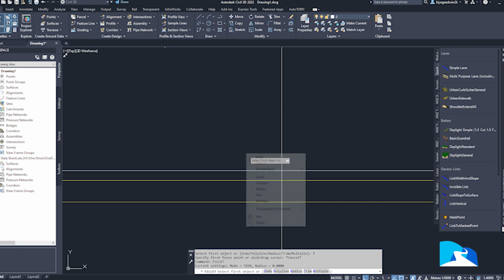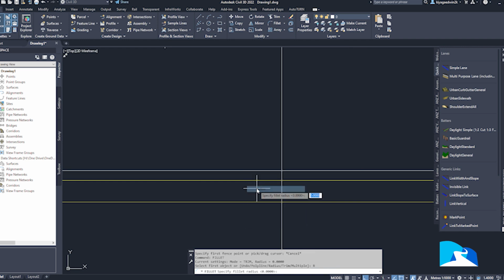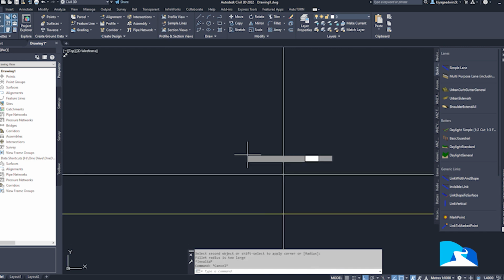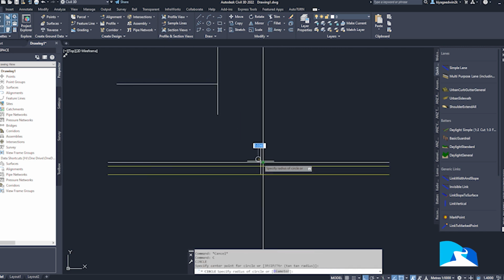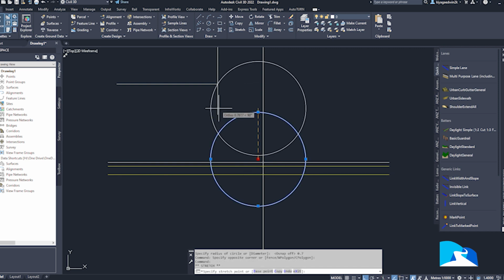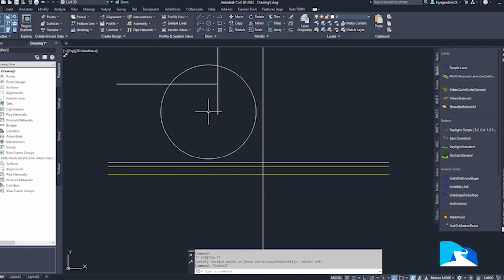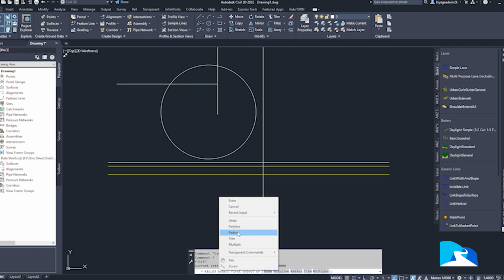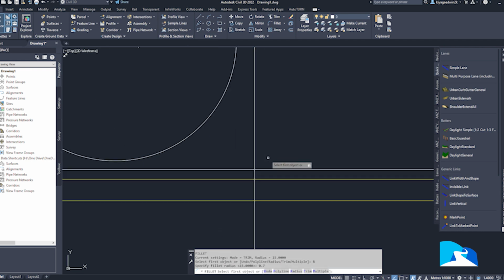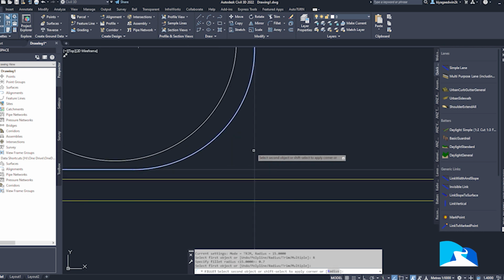Okay, and then you select, it's going to ask you for a radius, so let's say I want to fillet by radius of 15, so we select that and then we can fillet. Okay, maybe the radius is too large, so let's see what radius should I be using here. And F3, I drew something that was very small. Okay, so let's use 0.7 in this case, so we can fillet by 0.7. We shall be using this a lot. Okay, so when you fillet, you have that radius.